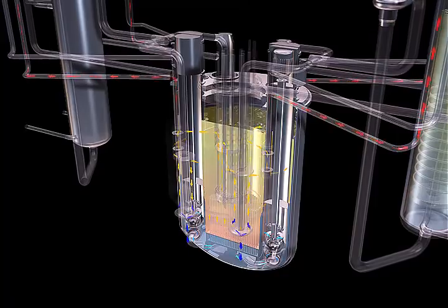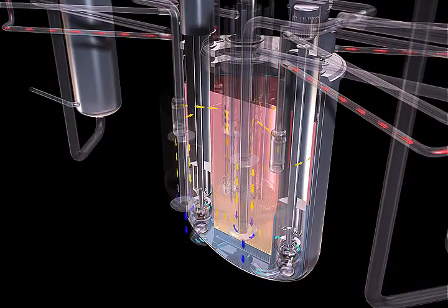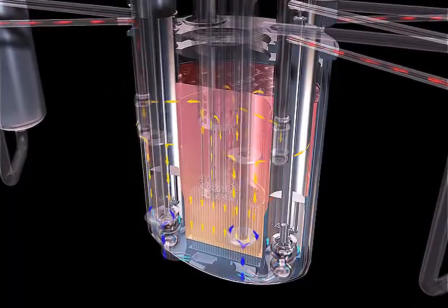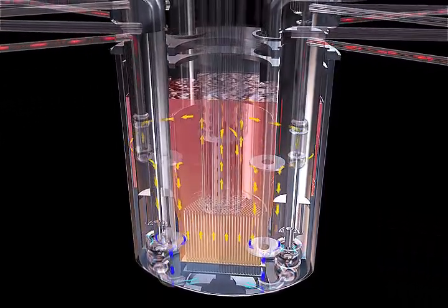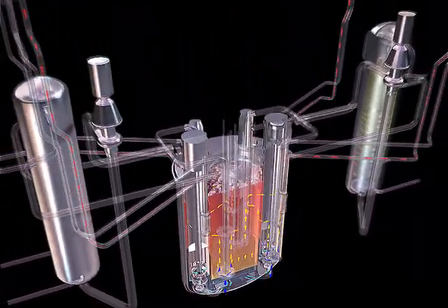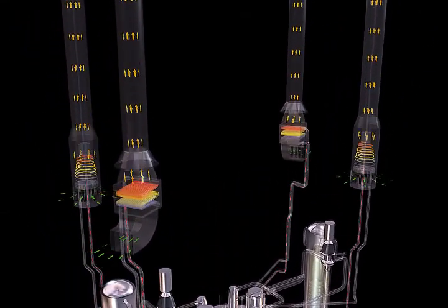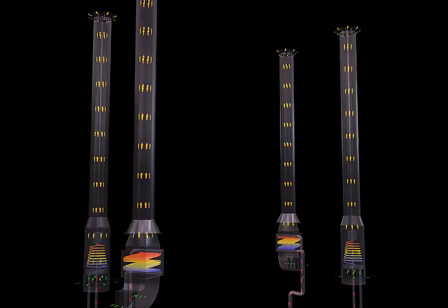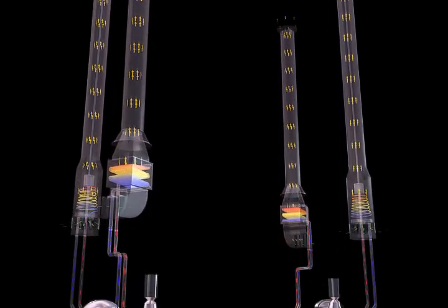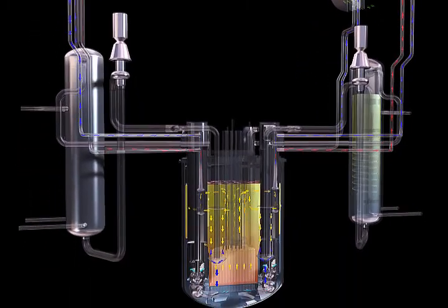However, since the normal heat transport system is not available in this event, a passive decay heat removal system starts its operation based on the unique design concept. This system, called PDRC, removes the residual heat effectively by a heat exchanging mechanism coupling with the density variation of the sodium coolant. Consequently, the core decay heat can be continuously removed into the final heat sink, that is, the atmosphere, without either operator's action or any power-operated components. The feature, totally based on a passive mechanism, makes the peak cladding and coolant temperatures stay below the design limit at all times.